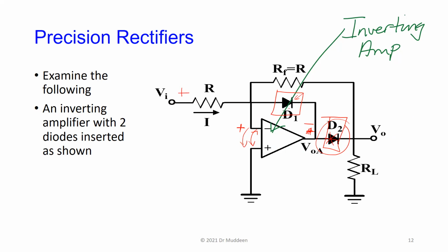And the circuit behavior, if this is pulled to ground, here goes to just about minus 0.7 volts, just enough to turn on this diode here. So the op-amp is doing the turn on behavior for you. And then after that, the rest of the circuit, it doesn't matter.